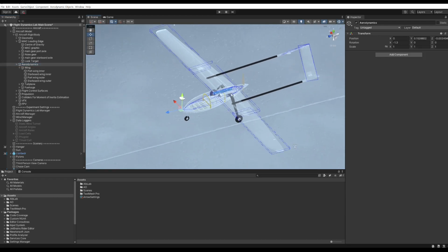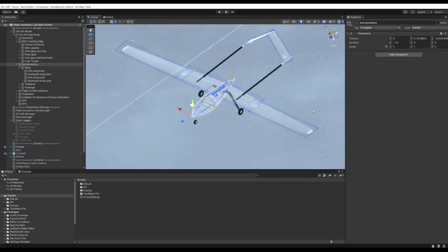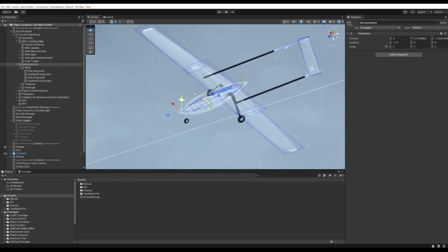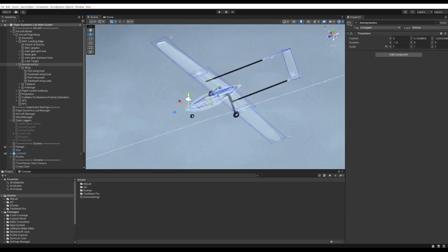I'm going to turn gizmos on now, and those blue boxes you can see there are the aerodynamic panels used to model the aircraft. It's done using blade element, and there's 4 panels on the wing and 2 panels for the tailplane, and they're scaled so that the area of the wing is right and the center of the panels is right, and the angle of the panels is right, so this thing has the right wing loading and the orientation of all the surfaces is correct. So it's a relatively simple aerodynamic model, but it's accurate at low angles of attack in terms